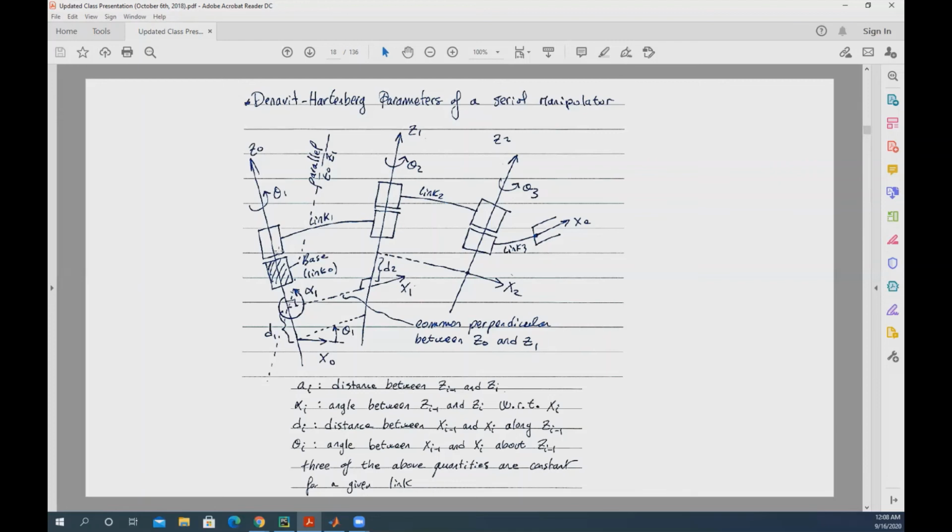Pointing in that direction. If you want the positive direction, you use the right-hand rule. Your thumb is the thumb of your right hand, not the left hand. You put your thumb along the axis, and then your hand dictates the direction of rotation. So this is my right hand, this is my z-axis, and this is theta. This is how the motor is mounted: this is the motor, the gearbox. Your z is along that direction, and this is your rotation direction.